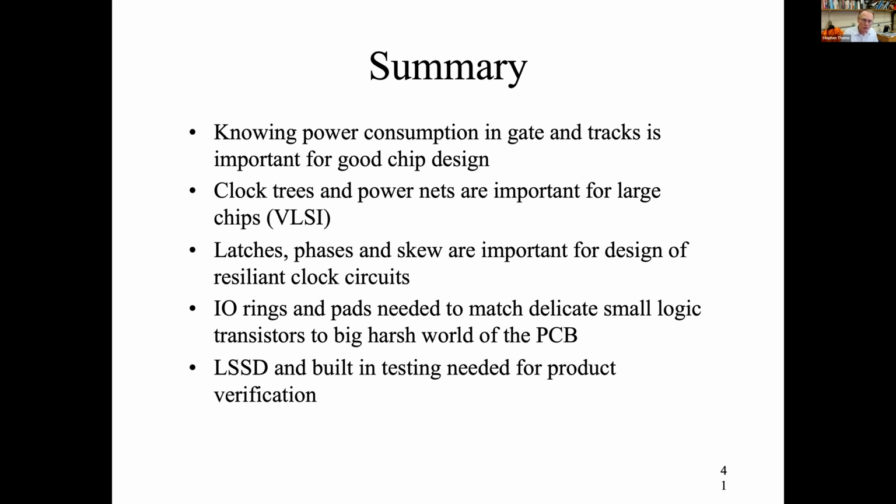We looked a little bit at I/O, the pads and the rings, because those are really important to match the internal logic with the big harsh world outside. And so it's important that you have these I/O pads. And when we talk about an I/O ring, the basic idea here is that around the outside of your chip, you have a whole ring of these pads, because typically you'll have many contacts to the outside world. And then finally, we had a quick look at LSSD, which is used for testing purposes to verify that the product actually works.